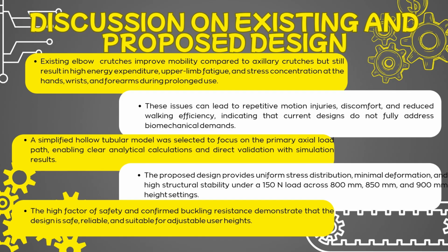For this project, a simplified hollow tubular model was chosen to focus on the primary axial load path. This allowed us to perform clear manual stress and deformation calculations and also directly validate them using simulation. Our proposed design ensures uniform stress distribution and efficient load transfer.